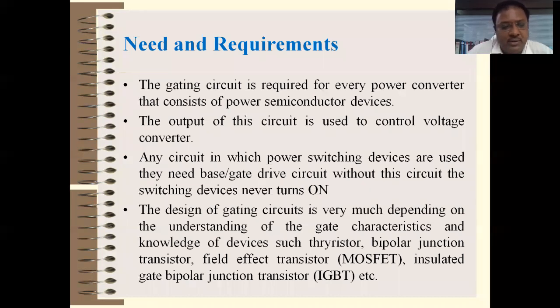So a proper gating circuit, or you can say drive circuit, is required in most of the power converter circuits. Microprocessor based drive circuits are used, so that the SCRs or the switching devices are triggered in a proper sequence. That is what we discussed in the last lecture, the need of drive circuits.